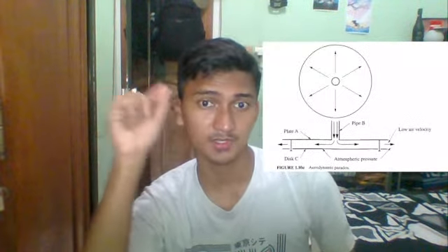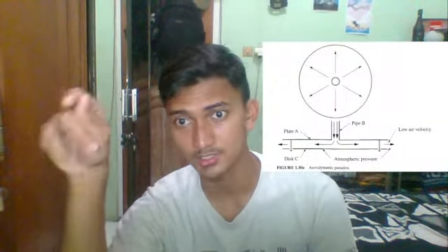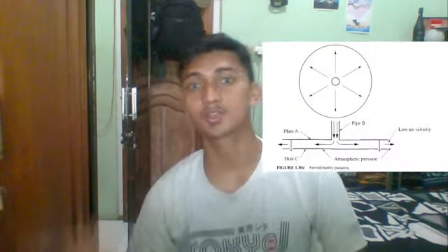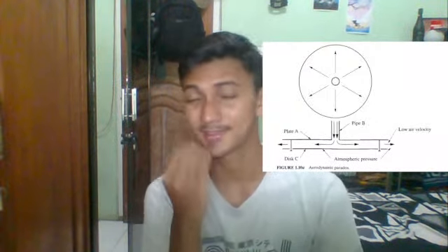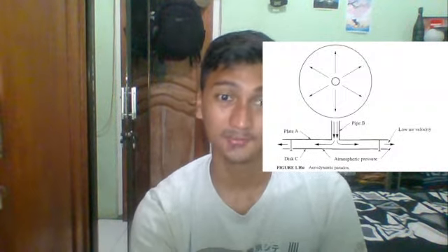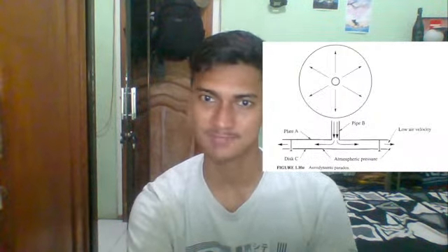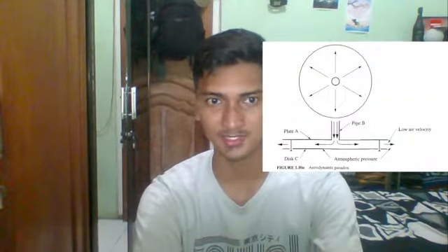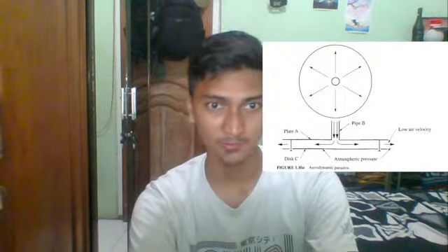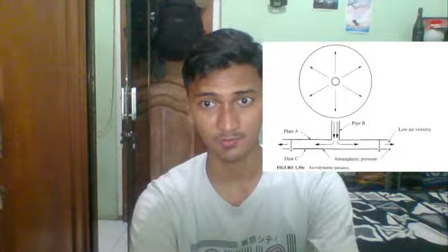The air stream leaving the pipe will turn 90 degrees and move outward since it has no other way to go. As it moves outward, the cross-sectional area becomes larger, as in a diverging cone, right? So the air velocity becomes smaller as the airstream reaches the outside of the disc. The air velocity will be quite small, and the static pressure at that point will be close to the atmospheric pressure of the surrounding environment, right?